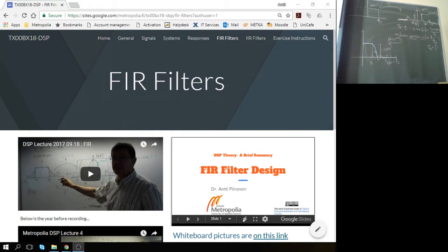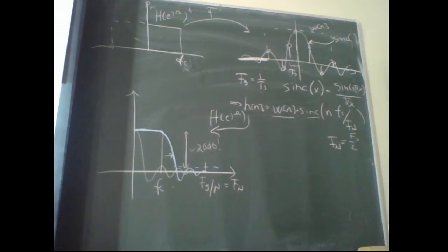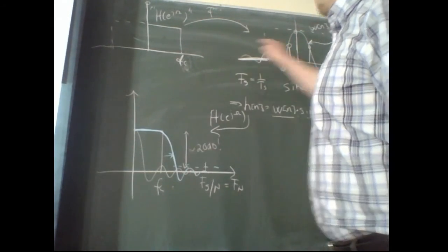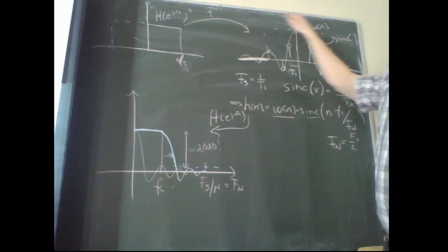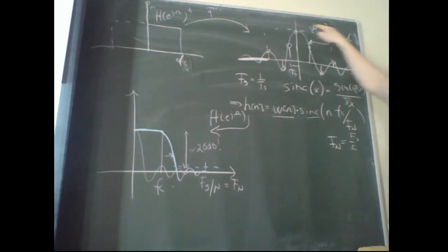Well, it's also the same as the attenuation of a running average filter. You don't get much better than that if you look at the definition of the low-pass filter. So, just wait a minute, I have the wrong kind of view here. Okay, better. So that's the attenuation of that window, which is basically the same as the average filter impulse response.